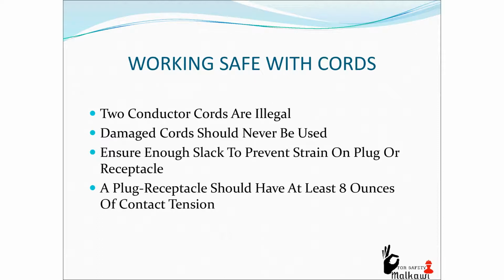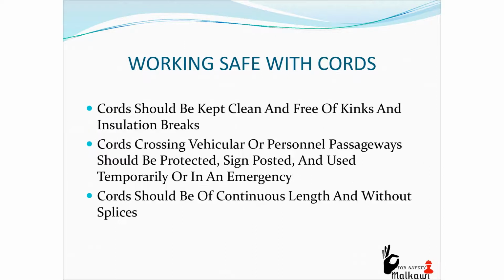Ensure enough slack to prevent strain on plug or receptacle. A plug receptacle should have at least 8 ounces of contact tension. Cords should be kept clean and free of kinks and insulation breaks. Cords crossing vehicular or personnel passageways should be protected, signposted, and used temporarily or in an emergency. Cords should be of continuous length and without splices.